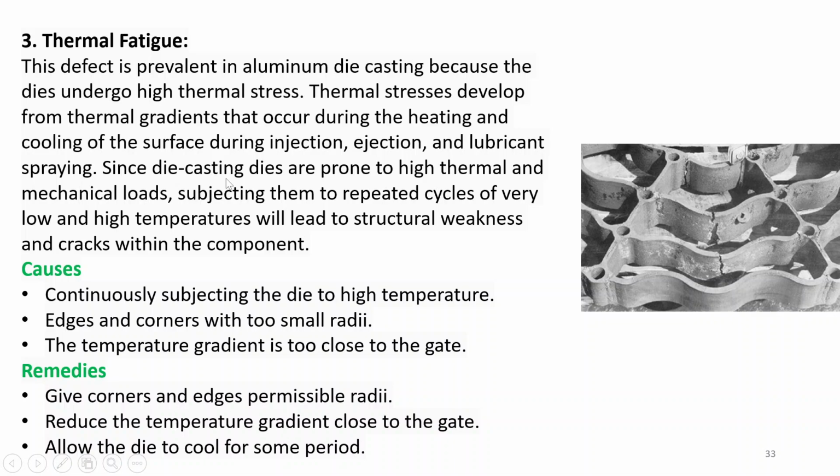Since die casting dies are prone to high thermal and mechanical loads, subjecting them to repeated cycles of very low and high temperatures will lead to structural weakness and cracks within the component.